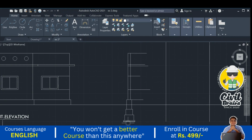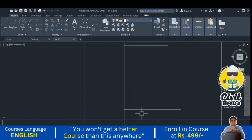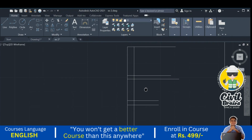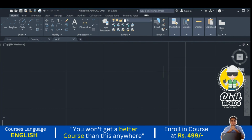So our PCC, first step, second step, plinth, and above the plinth the superstructure or the wall. Okay, so here the window. This is our sill level and this is our lintel bottom level. Above that we need to provide the lintel. I just offset, press enter. What is the thickness of the lintel? 0.15. I need to provide the lintel over here. After that the slab and further the parapet.